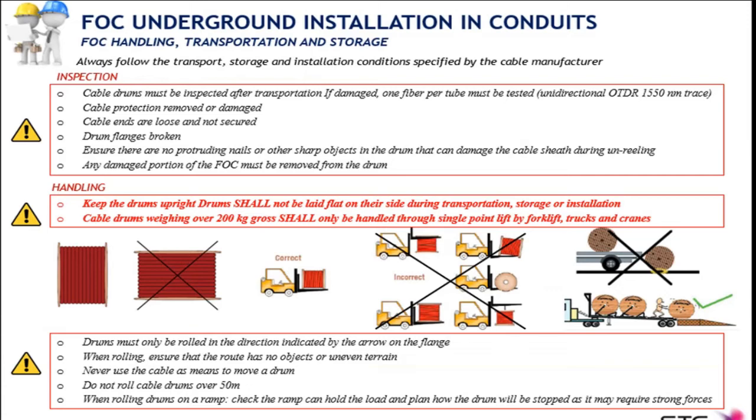Regards cable drums, they must always be inspected when first delivered by the manufacturer to the contractor's warehouse, also when transported from the warehouse to the site. Always inspect the cable drums and look for protections removed or damaged, cable ends loose and unsecured, drum flanges broken.